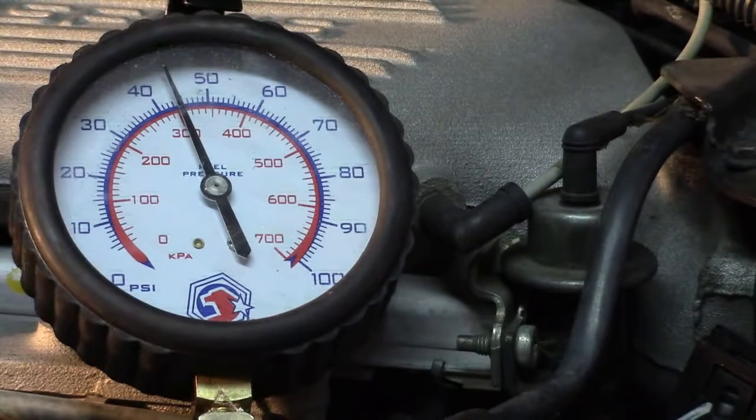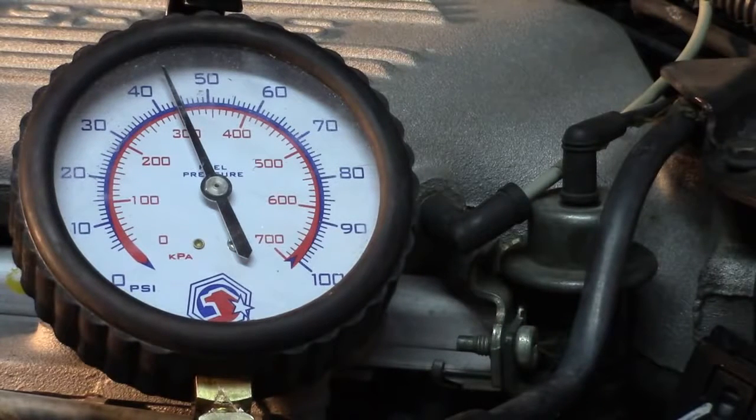What does this tell us? This tells us that we do not have anything like a leaking fuel injector, external fuel leak, or anything like that. It also tells us the fuel pressure regulator is probably also not leaking. It is also indicating that the fuel pump check valve, things like that, are not leaking. If we do see a drop here, then hang on, I'll tell you what you would do to diagnose what's wrong if you saw a drop at this point. But since we don't have a drop and we know that we're safe, I'm going to go ahead and start the car. Let's see what happens.